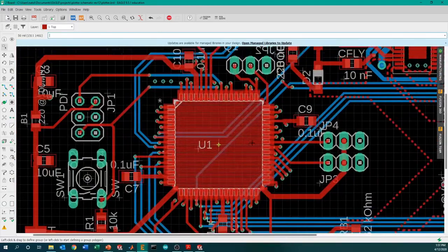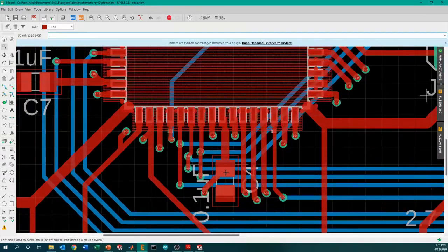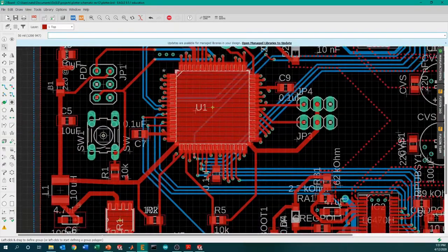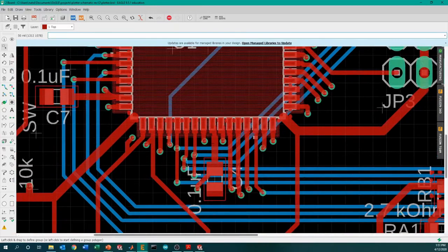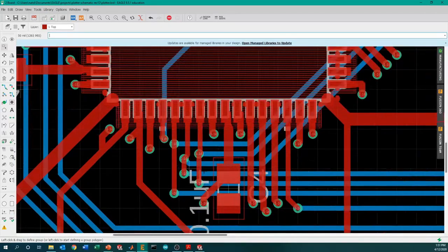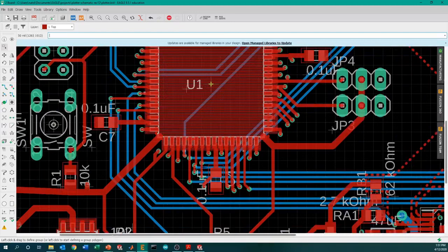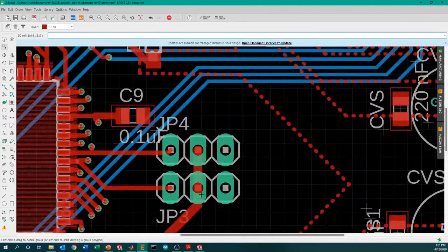And like I mentioned earlier, we connected absolutely everything on this microcontroller, or almost everything, up to vias, which ended up being super useful, as we did swap the MISO and MOSI pins around, which was not good, and did not allow us to use the software SPI, and the bitbanger we wrote was not very friendly with FreeRTOS, so we ended up just having to swap those over, and having a little extra vias here was super useful. And then finally, our servo header pins simply located over here.